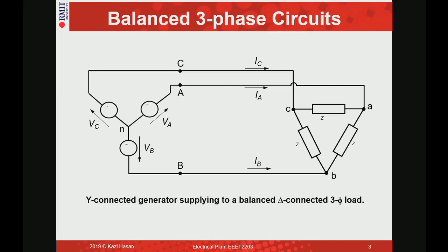In our real life, in reality, as we said, the high voltage system is three-phase, but when it comes to our home, we are on single phase. So when they give connection in a distribution feeder, three single phases, consider your street, maybe all of the houses connected in one phase, phase A, your neighboring street in phase B, and another street in phase C. So what happens, definitely all of these streets are not consuming the same amount of power.